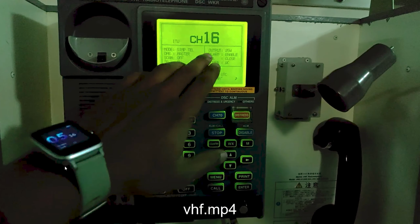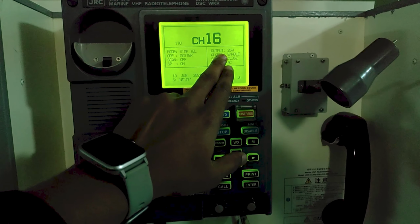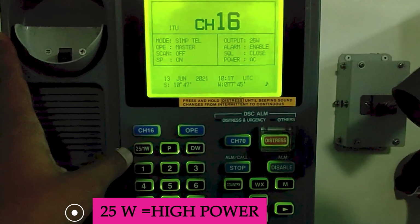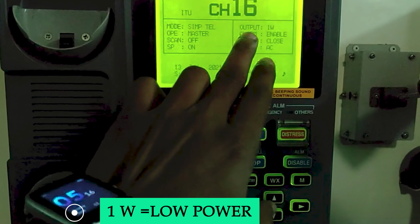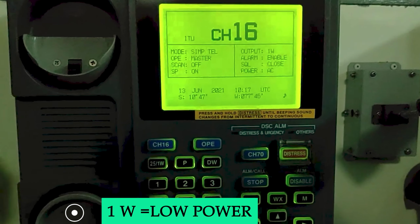Here on the VHF screen you can see near the output, beside it, it's written 25 watt. So now it is on high power. To make it low power, there is a button 25/1 watt. We'll press this and now you can see beside output it is on 1 watt. This is what we have to do in cargo operation, make sure it is at 1 watt.